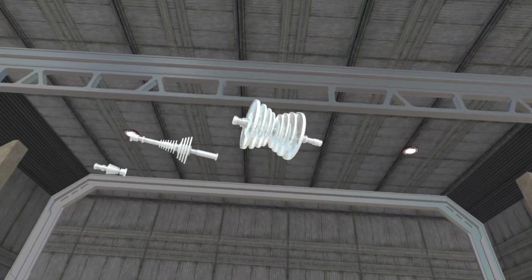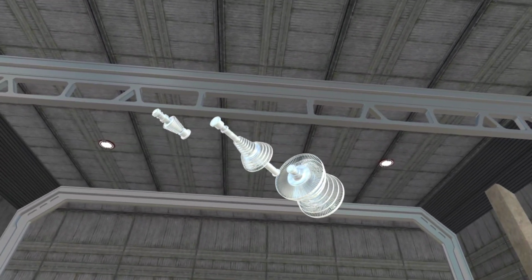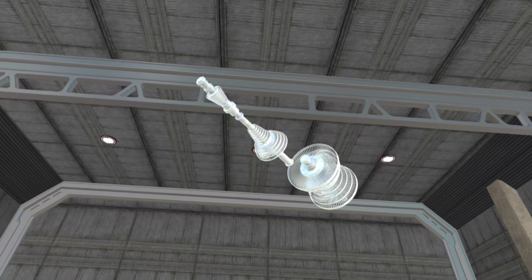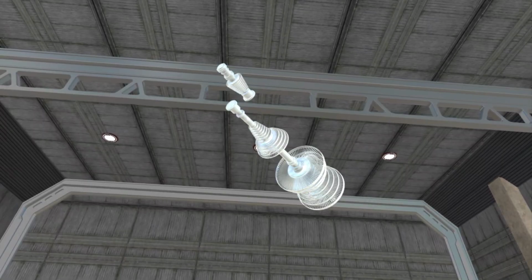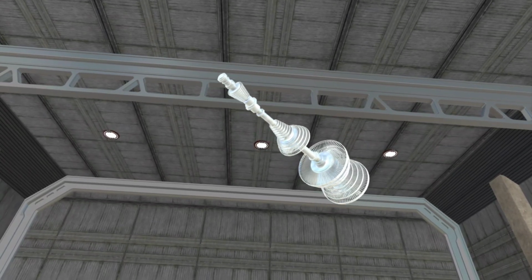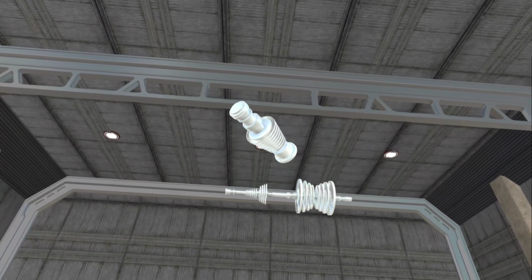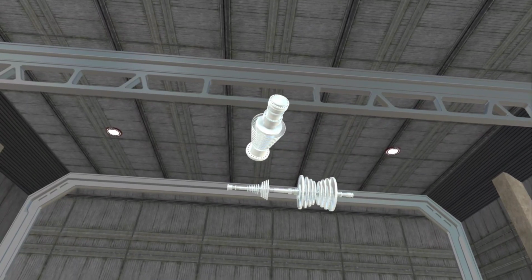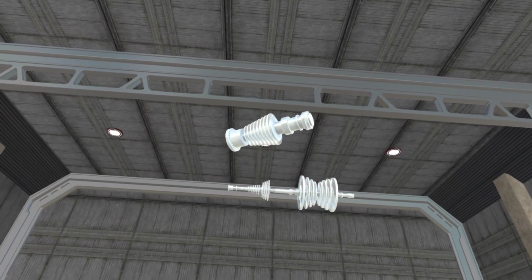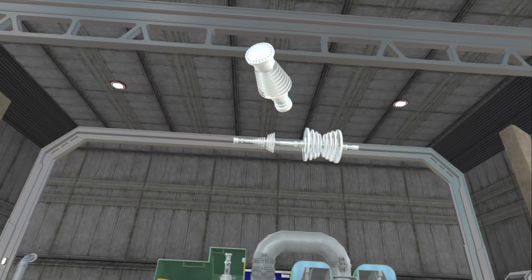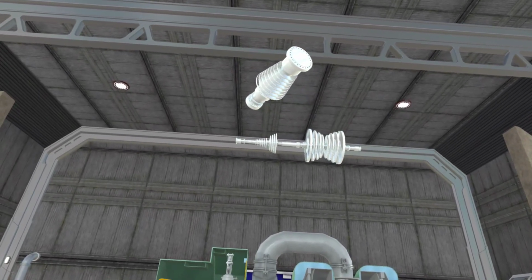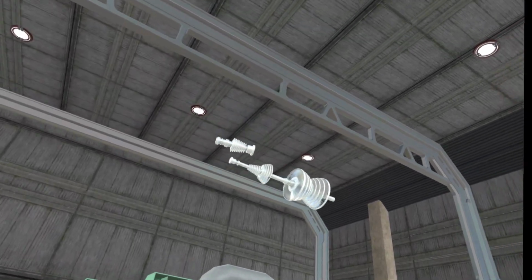High-capacity power plants use various stages of steam turbines, such as low-pressure steam turbines, intermediate-pressure steam turbines, and high-pressure steam turbines. A high-pressure steam turbine, or HP turbine, is the first turbine that receives the main steam directly from the boiler. It is specially designed to extract work out of the very high-pressure steam.